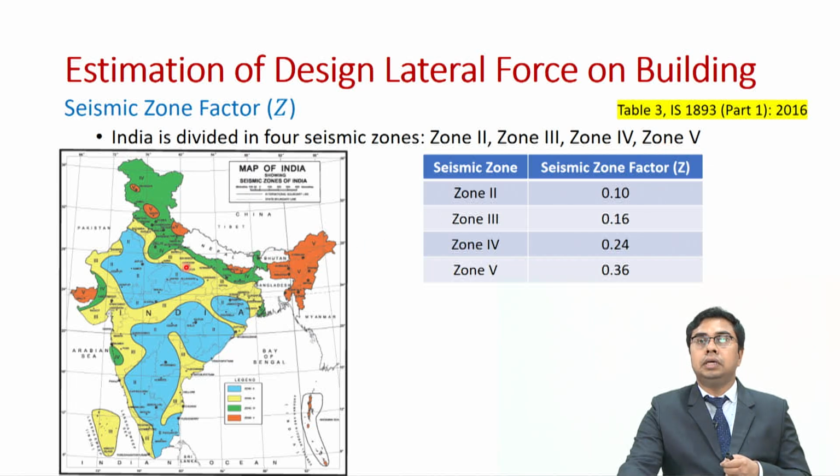So, as you would be able to guess that some regions in Himalayas as well as the northeastern India have higher seismicity. So, they are assigned zone 5. On the other hand, the peninsular India has lower seismicity, and therefore, you will find that they are assigned a lower seismic zone. Now, this is also based on historical seismic data of various regions, that is based on occurrence of past earthquakes, their damage intensities, etc.